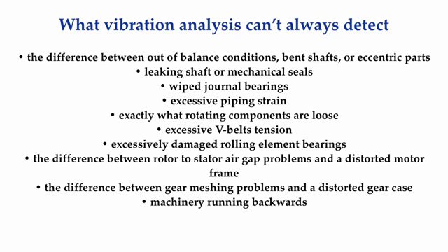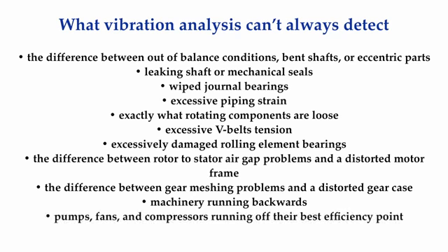Vibration analysis cannot detect if a machine is running backwards. It cannot tell you anything about the operational efficiency. Vibration analysis is also not very good at detecting how severe the misalignment is on a drive system.